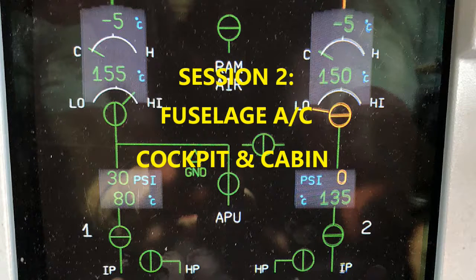In automatic operation, there's really no need for any intervention. But there is an opportunity to be in a manual operation. You have that toggle switch that controls the manual motor of the outflow valve, and that's selected by the pilot in the cockpit with the MAN selector pushbutton switch. Selected to MAN for manual. So that's possible there.